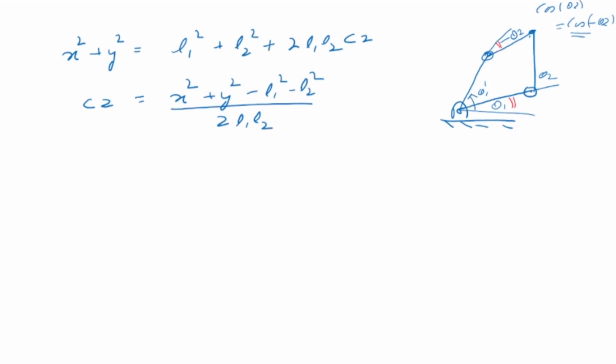What I'm trying to say is, if you take theta 1 and you take the other one, theta 2, that will actually not match. What will happen is that your manipulator will become like this, so there is no connection here. Why? Because this is my theta 1 and that one is my minus theta 2. Because of this problem, we do not take the inverse of cos.